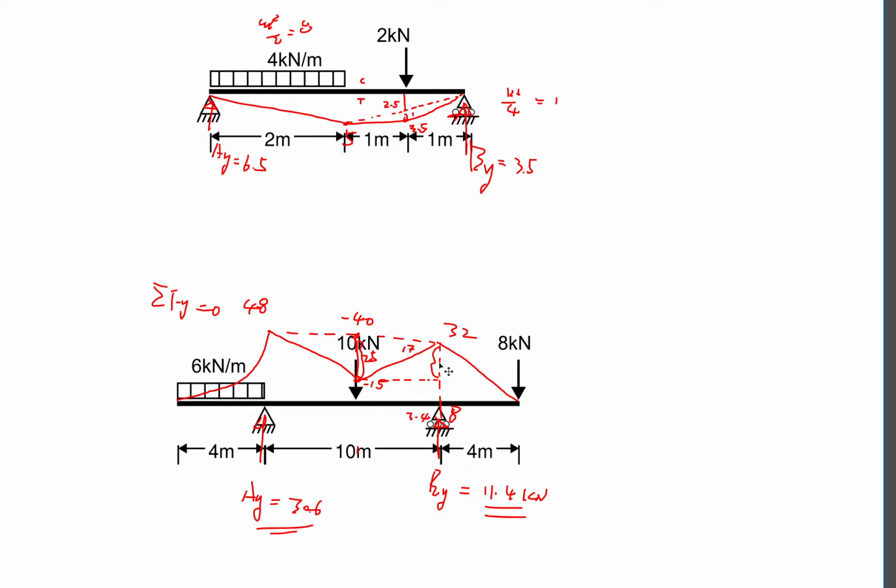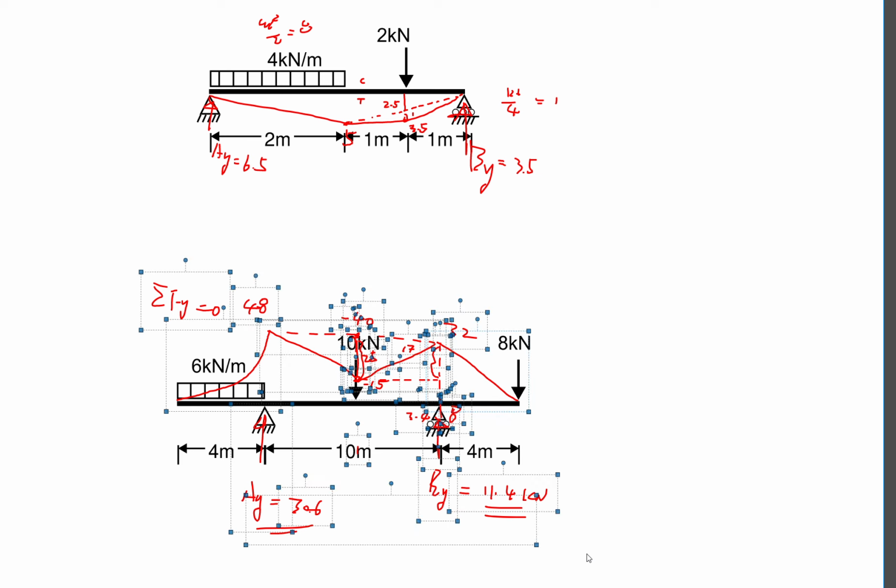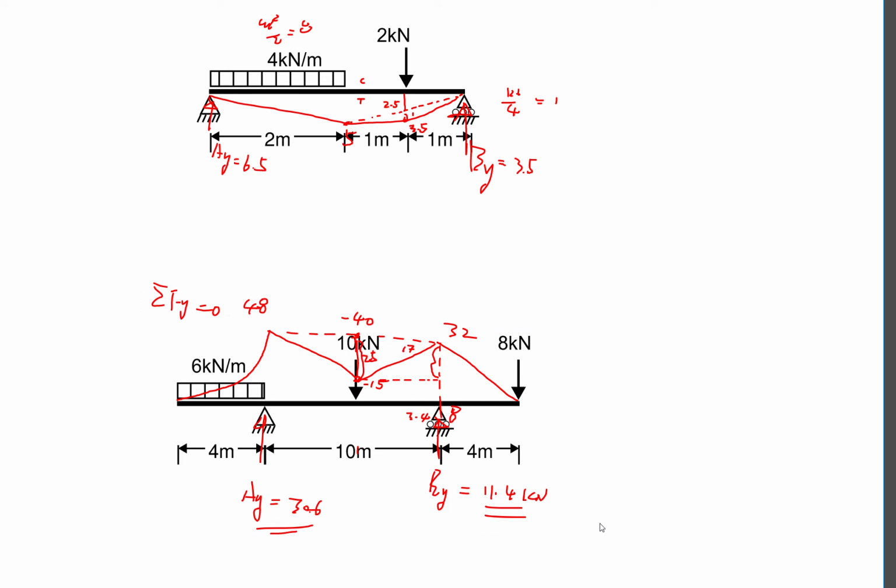Remember that your bending moment is the integral of the shear, and your shear is the derivative of the moment. So when you have a linear relationship, just using the moment divided by your distance gives your reactions. So this is a really good example to practice on.